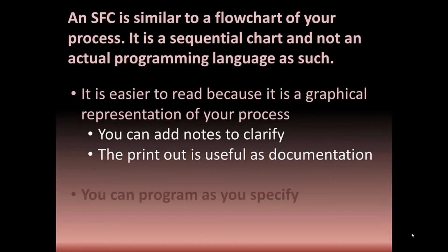And then another added advantage is that you can program as you specify. So you could sit down and create a sequential function chart in RSLogix 5000, and as you actually create the sequential chart, you can actually do programming, write in the individual steps and actions as you go, and that kind of helps clarify the process.